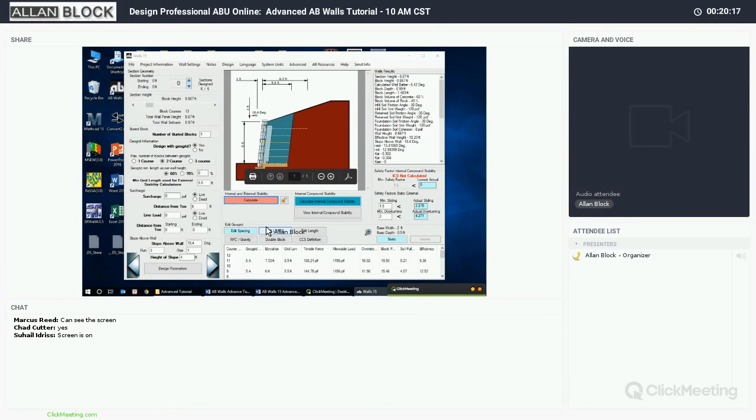I'm not endorsing it at all, but it does make it a lot easier to drain that through. So instead of coming through the block itself, you're pinching this Wall Drain Pro. It's 1 3/8 inches wide, so you're pinching it between two units, and it's a nice, clean, simple look. But again, I'll provide some information in the follow-up email about it, especially with the rules that OSHA has passed about silica dust generation. We've got to try to minimize how much cutting we're doing on a job site. This makes it really easy to do that.